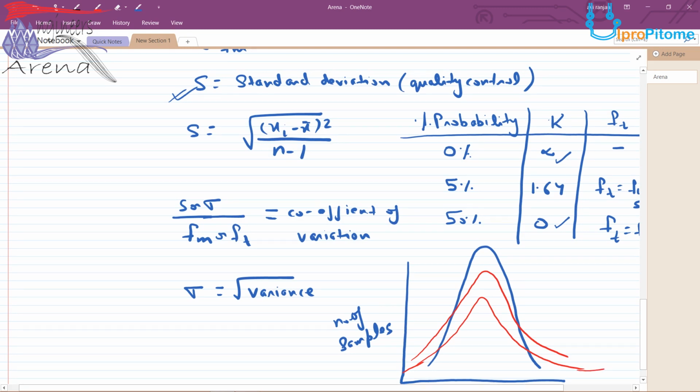Then which one will be the best sample? This blue one you plotted for one lot, the red one for another lot, and this for another lot. There were 3 lots from the batching plant, and you plotted for all the lots. Then which will be the best one? The one more closer to fck. This will be the good one, this will be average, and this is worst.